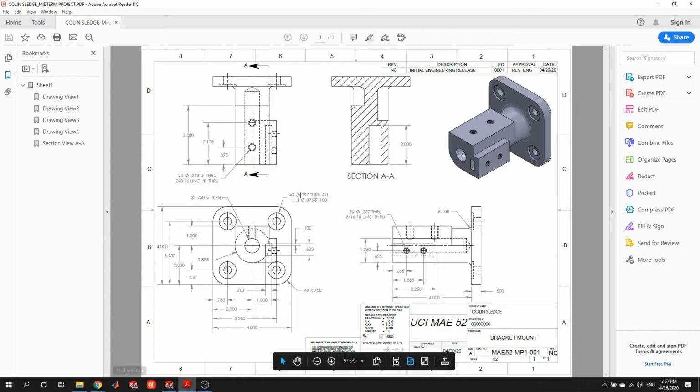Okay, excellent. So now what we're going to do is actually, from this face of the cylinder, build backwards. And if you look at the part, you can see that there's 2 somewhat rectangular extrusions. And I know it's a little hard to see that they're rectangles now, but it'll make sense in just a minute. And each one has a different depth of extrusion. So let's work on the larger one first. It's really important to notice, both from this view and this view, that this meets up tangent to the edge of the circle in both cases. That's going to be how we dimension it.